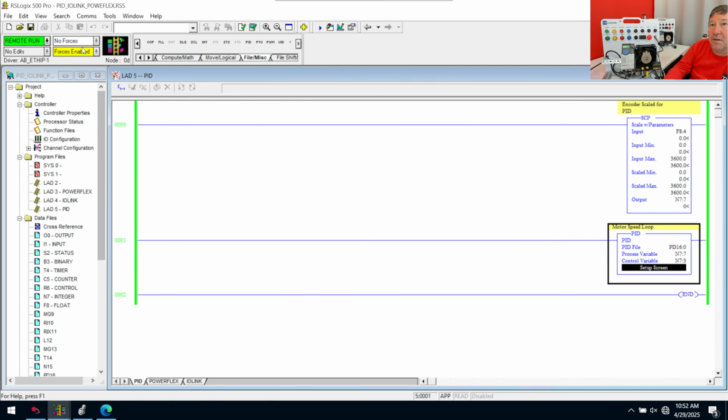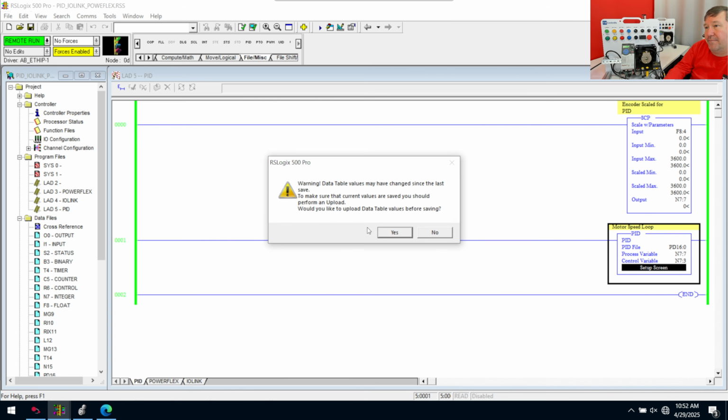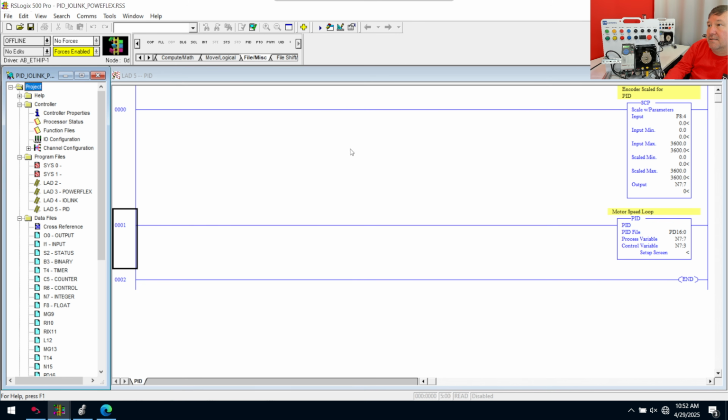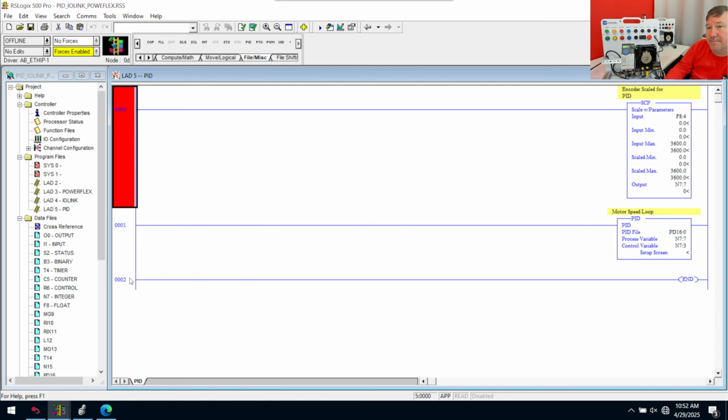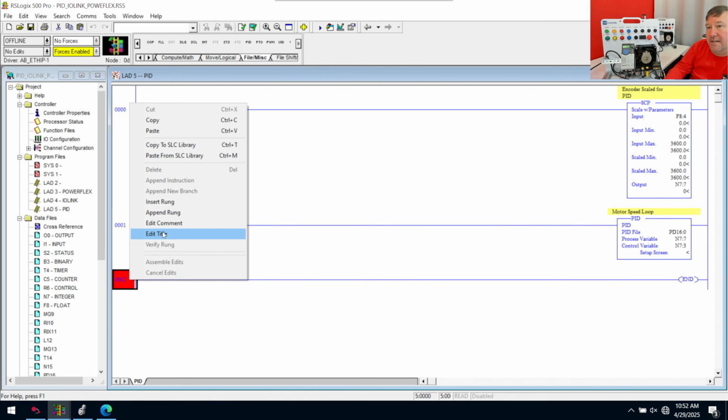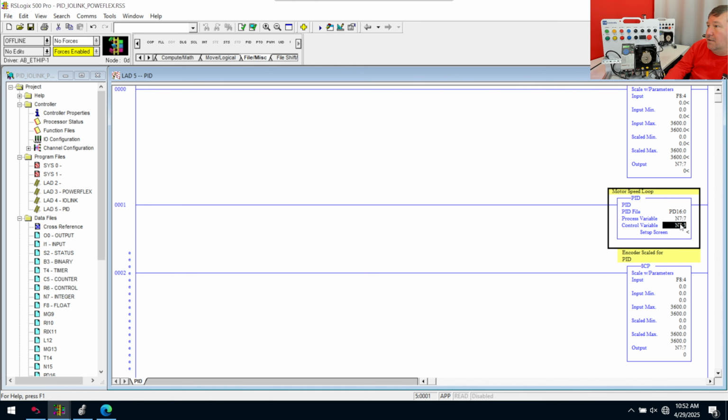So we're going to need to go offline. And we can do this online, but we're going to need to do another SCP instruction. So we're going to communications, go offline. And we've got enough of it here that we're going to start with this. We're going to copy that. Now we're going to paste that here. Now, our output, we need a different tag for this one.